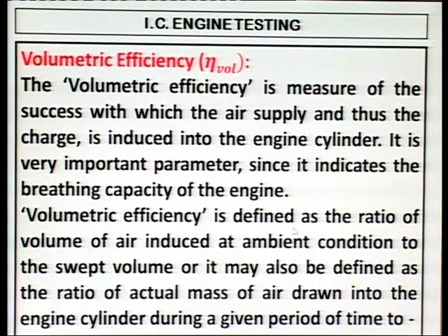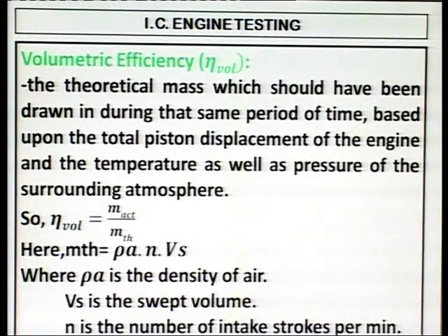Volumetric efficiency is defined as the ratio of volume of air induced at ambient conditions to the swept volume, or it may also be defined as the ratio of actual mass of air drawn into the engine cylinder during a given period of time to the theoretical mass which should have been drawn in during that same period of time, based upon the total piston displacement of the engine and the temperature as well as pressure of the surrounding atmosphere.